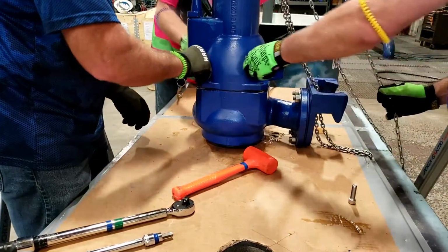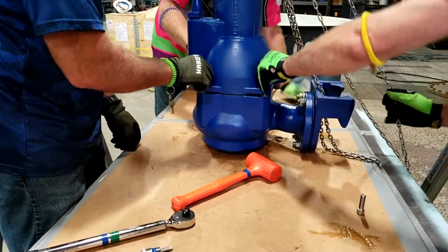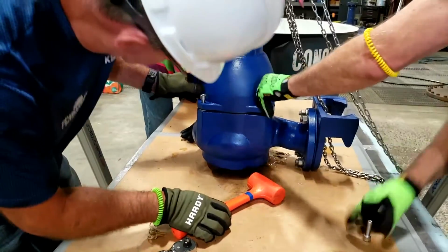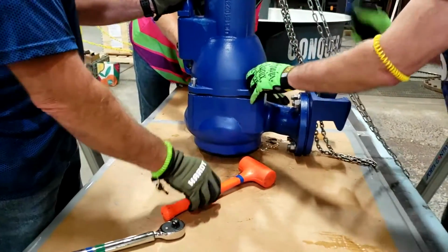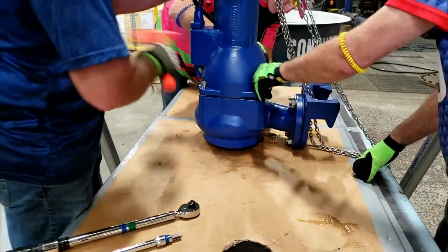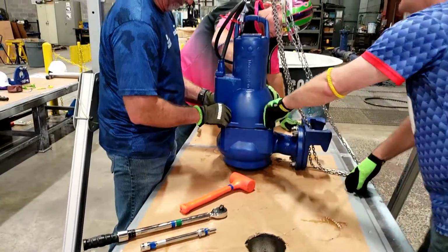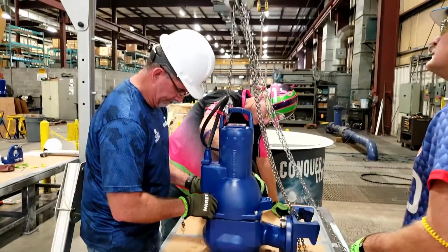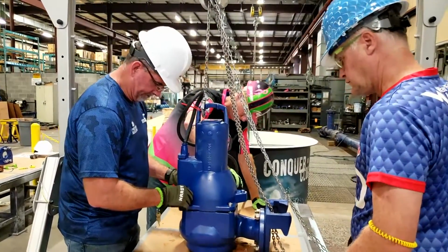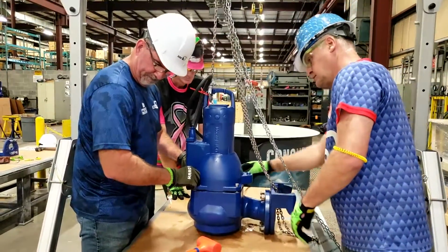Reinstall the 4 new 10mm volute hex socket bolts hand tight. You also need to ensure the washers are installed as well, such that from the top to the bottom, that is the volute bolt, pump flange, washer, then volute. The washers will be loose and not permanently affixed to the pump or volute.